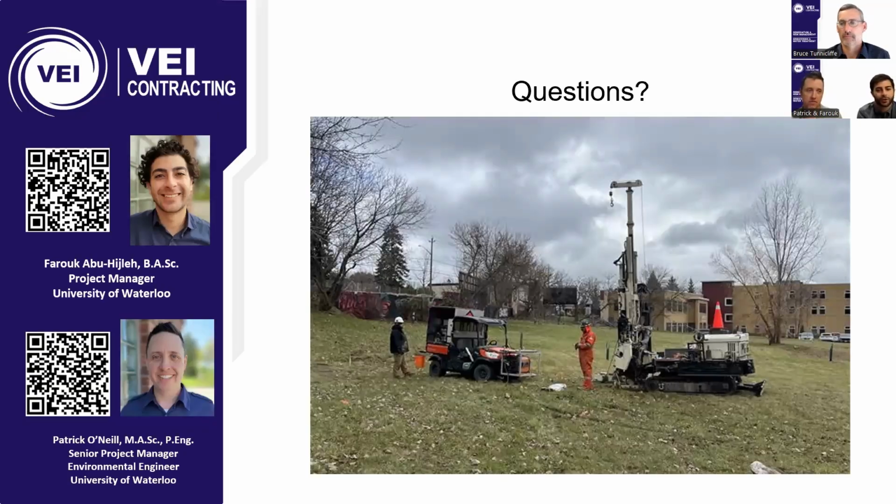Yeah, let me approach it from a different perspective from the dewatering perspective. If I'm doing a test in a tight material like a silt or a till, it's going to take a long time. I already know that there's not going to be a significant amount of water being produced from a dewatering perspective, right? I'd rather go chase the sand seams that are going to make trouble for me when I get to the dewatering stage. You're better off if you identify that silt till layer, you have the geoprobe on site, put a well, hang a data logger, and come back in a couple of days and get the data you need that way. Yeah.